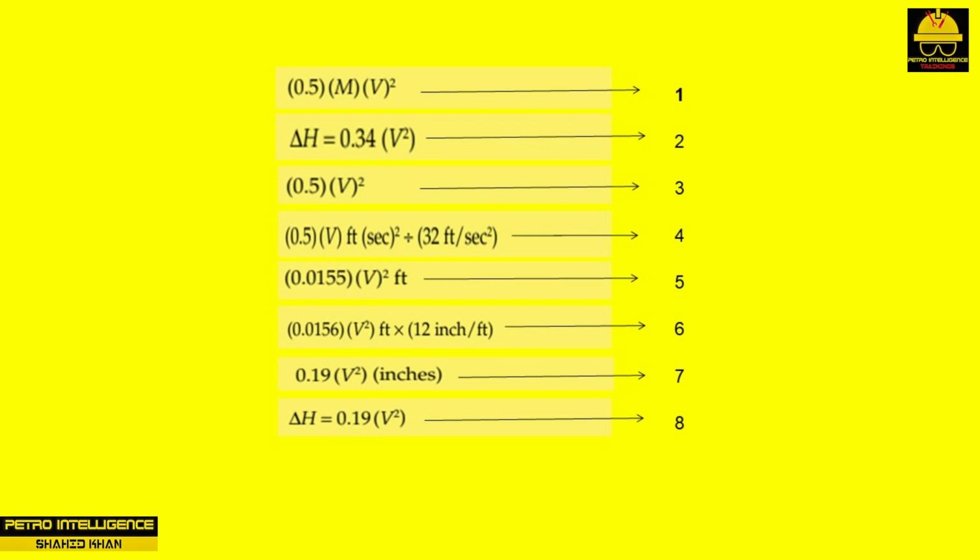The difference between the 0.19 coefficient in this equation and the 0.34 coefficient in the other equation is due to friction losses through the nozzle and my safety factor used for design. All I have done with the above calculation is convert kinetic energy into potential energy. The purpose of this calculation is to demonstrate that there is a real theoretical basis for some of my basic rules of thumb. One of the best ways to improve one's engineering skills is to compare, on a quantitative basis, engineering theory and practice.